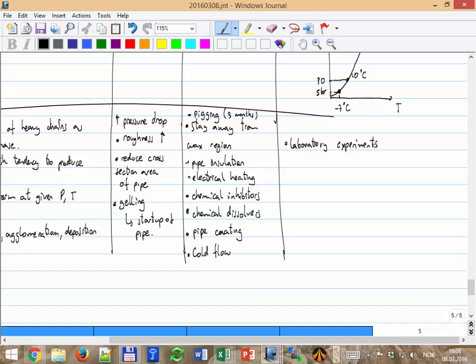For example, the case of Snohvit. They were concerned about hydrates, so they did chemical injection, injection of methanol, but there was no problem with wax. They weren't going to have any problem with wax, so that's why you have only one pipeline. If, on the other side, they had wax problems, then they would have to build two lines to do pigging, and maybe that would have been uneconomical. So they were lucky.